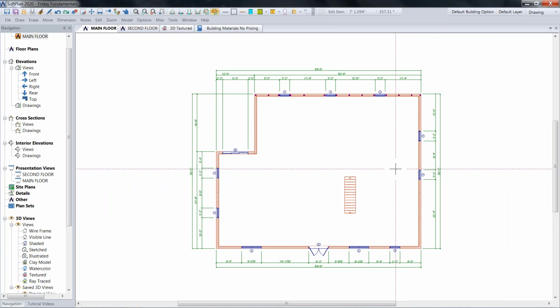So I gave you the jet tour of doing a two-story dwelling, block first, stick second, using automatically rising stairs, finding their floor-to-floor distances, calculating everything that's going to be required, including in a Florida environment, the filled cells, the downpours, and all that stuff. We put a roof on it really quick, and we changed one end to a gable end, and we ran a bill of materials takeoff report.